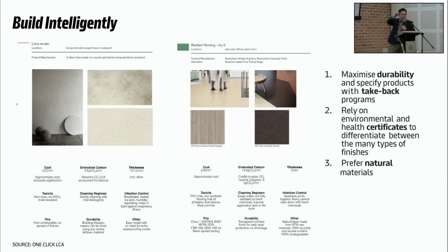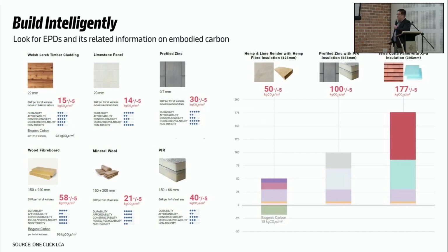If you notice just now, you have the GWP biogenic. Any use of wood product will score an offset value, because the wood gives a negative CO2 contribution. Other examples like this, where I look at the GWP over here, all these, the red color ones are the GWP. When you are presented with data like this, you can pick and choose to suit your design. You may not necessarily choose the lowest one, but at least you know where you are. All right?